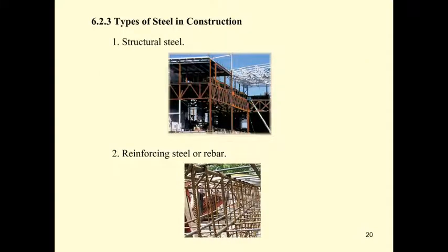Okay, next, the steel that's used in the construction mainly separates into structural steel, like I said, from the production. When it's hot rolled, you may get the W section, which is the H section. This is American, this is Japan, or the I going to be like this. W and H are going to have equal width and depth, but for the I, the width is smaller than the depth. This is the I.